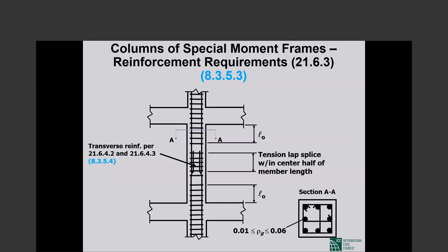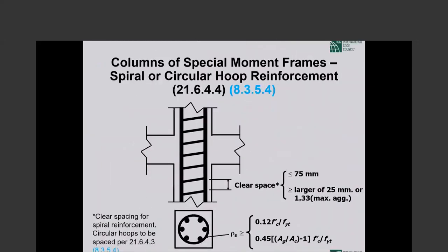So you are so much better off if the column reinforcement is light. Then you don't have so many legs of hooks and cross ties and so forth. Okay, so it is absolutely paramount that you understand that the column reinforcement has to be the lowest practicable. You cannot always have just 1%, but it is good to stick close to 1.5% to the extent that it is possible. I cannot overemphasize the need to keep column reinforcement light in high seismic construction.